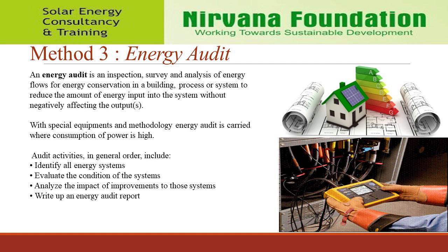Energy audit. An energy audit is an inspection, survey, and analysis of energy flows for energy conservation in a building, process or system to reduce the amount of energy input into the system without negatively affecting the output. With special equipment and methodology, energy audit is carried out where consumption of power is high. Audit activities, in general order, include: identify all energy systems, evaluate the condition of the systems, analyze the impact of improvements to those systems, and write up an energy audit report.